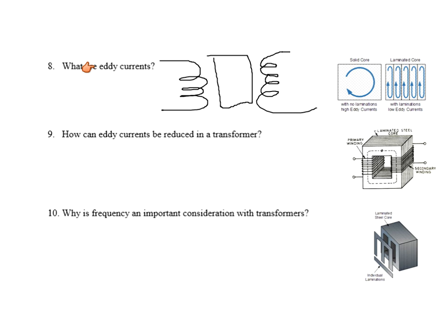Now, eddy currents can be reduced by reducing the size of the conductor of the core. The way that we do that is we take the core and slice it up and put insulation between them. These are said to be laminations. Therefore, you're getting smaller, tiny currents in each of those little slices. A laminated core looks like this. You can actually see slices of metal, but there's this little plastic insulation in between them. It still works like one big core, but the eddy currents are minimized inside. And down here you can see, here's a laminated core, and in between these slices are insulation.